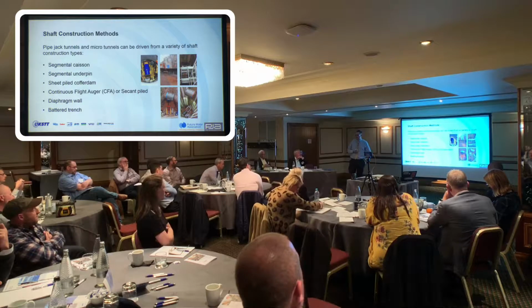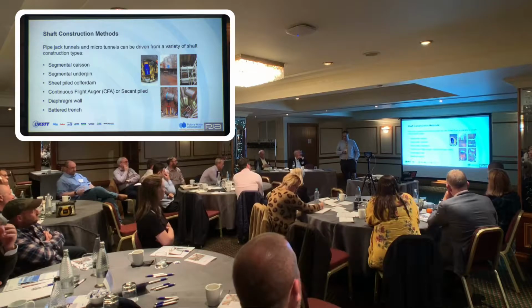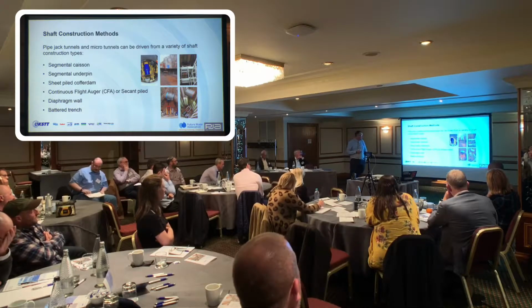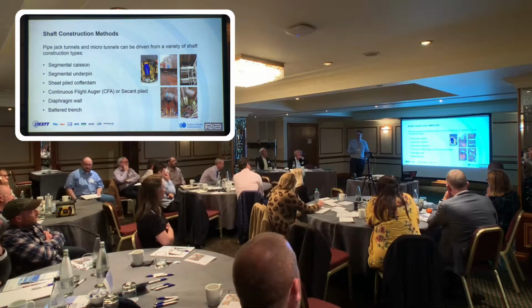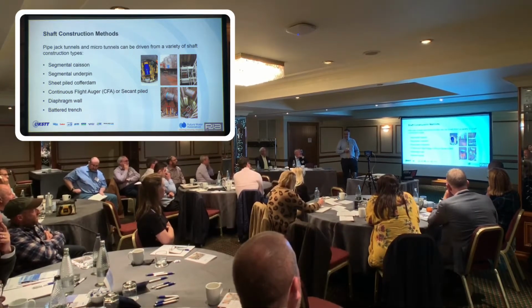Obviously, settlement and heave are big considerations, but if you were to get a little bit of settlement going under, say, a green field where you were just trying to minimise disruption to the public, to the flora and fauna, that wouldn't be as critical as if you were going under, say, a railway where you were predicting large amounts of settlement and then risk to the rolling stock.